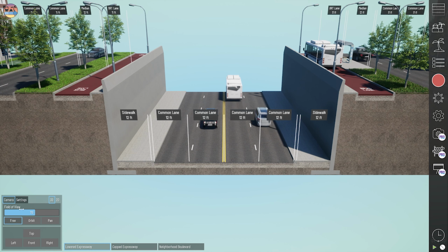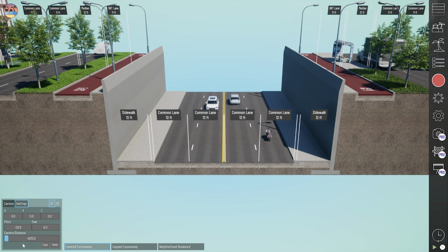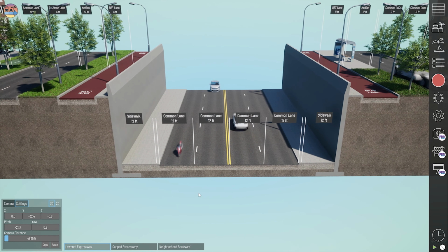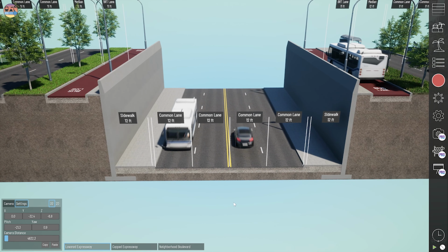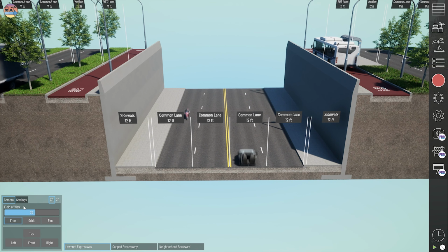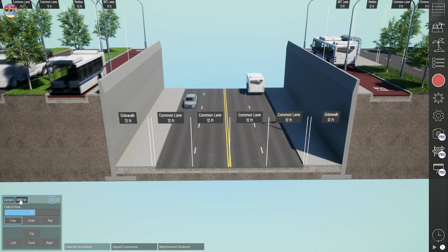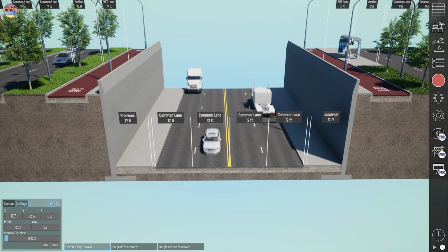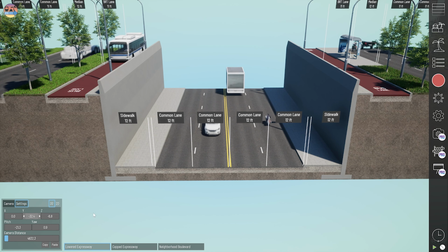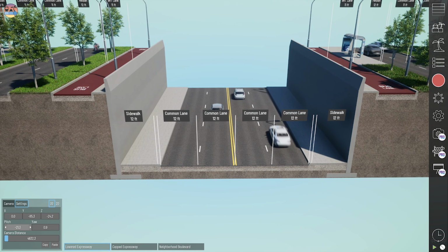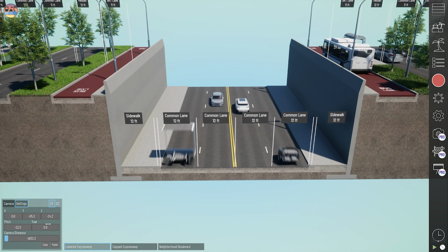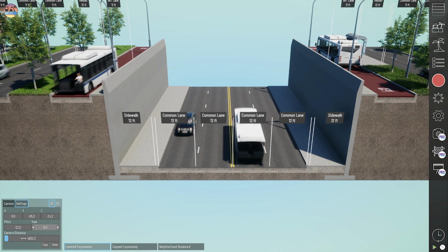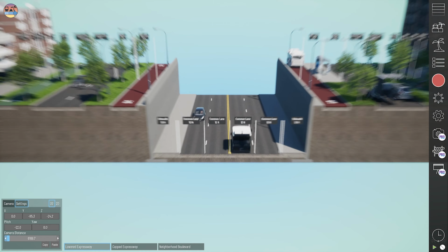We've added some new camera control settings in version 2.4. These tools will definitely help you line up your camera to an imported image when using the photo compositing tool, but they can help with other specific camera position needs as well. You can access these by clicking the Settings button in the lower left of the screen. These tools allow you to see and edit the X, Y, and Z coordinates of the camera, plus change the pitch or up-down angle and yaw or left-right angle of the camera. The camera distance setting zooms the camera in and out.